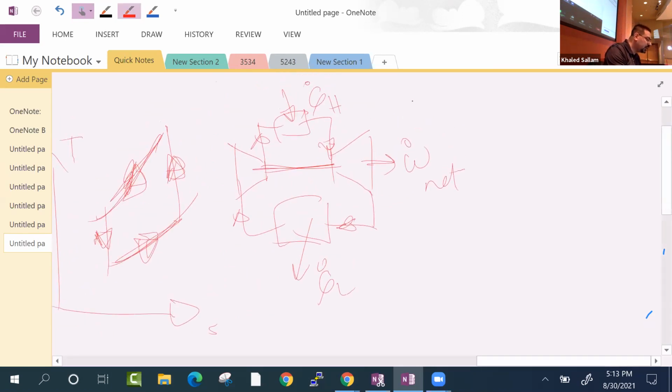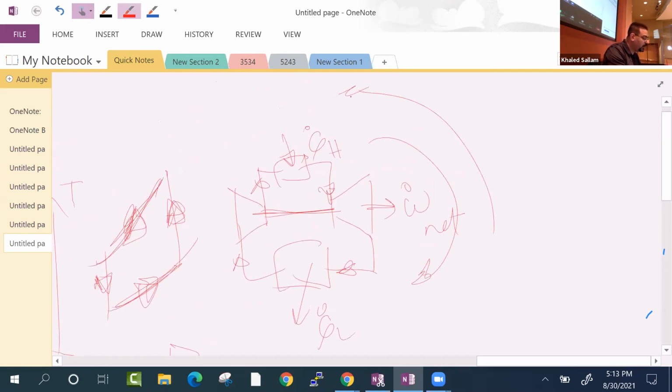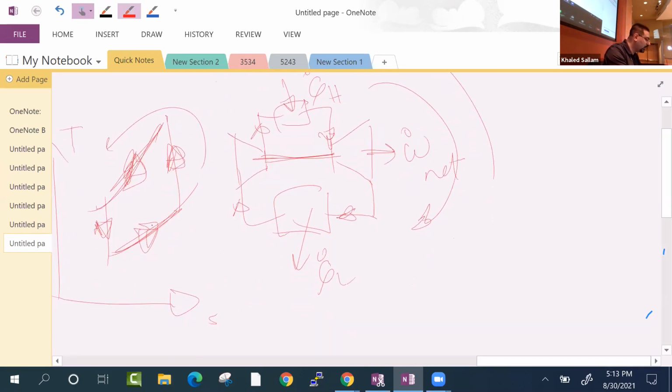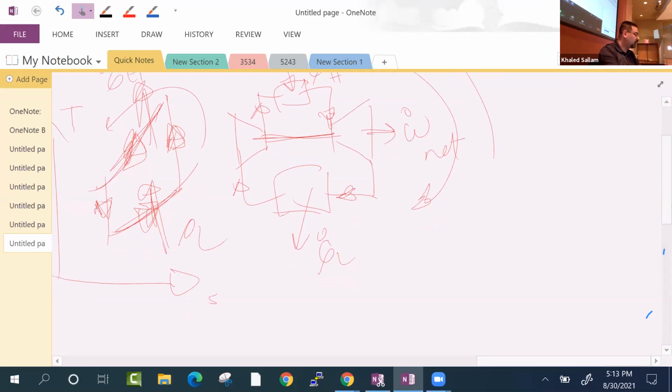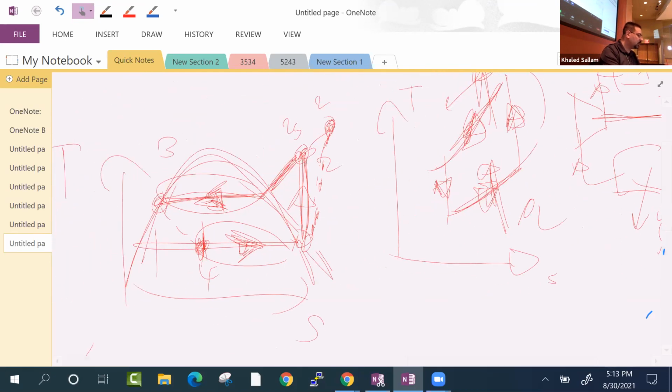So if it runs this way, that's a Brayton cycle, we get work. But if it runs that way, it's a refrigeration cycle, and it will be like this. And what you get from it, you get QL sucked from and thrown to QH. So you get a refrigeration cycle by reversing the Brayton cycle, right? So this is done.